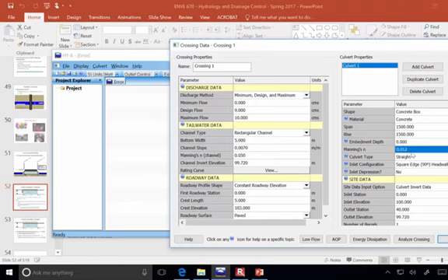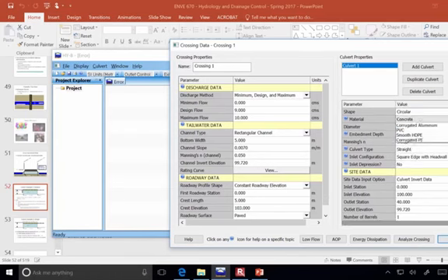I'll leave the embedment depth, all these defaults here for the n value of concrete. I'll have it be a straight culvert. If you change the material, I think it'll automatically change the n value. Concrete's the only thing you can have for a concrete box, but for instance, if we had circular, we could change to corrugated steel, and it would give us a new n value, depending.